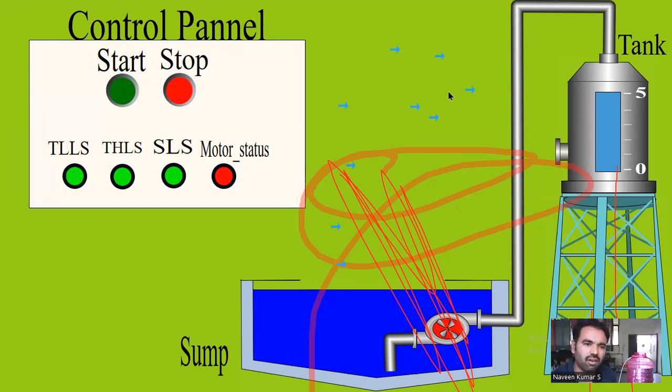We have to create all these screens from the application, right? We have used just one serial cable between the PC and PLC. Even though we have used a serial cable, it uses another protocol called Modbus, which can be seen while developing the SCADA screen.